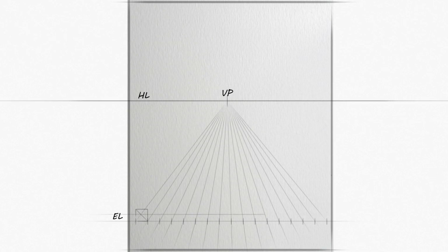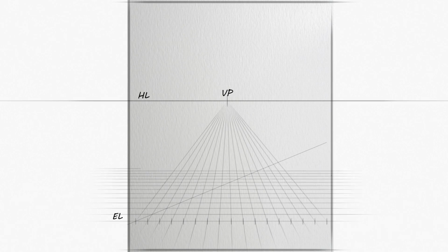Draw a horizontal line exactly at the intersection where the diagonal of your initial square crosses the radiating vanishing line, as shown. Next, trace an extended diagonal line running directly through the corners of the resulting rhombus. With this guide in place, you can now project all the remaining horizontal lines across every intersection where a vanishing line meets this main diagonal. To expand the tiled floor further, draw a subsequent diagonal as shown, and project the newly required vanishing lines outward from the main VP. Finally, replicate this exact sequence on the opposite side to complete the grid.